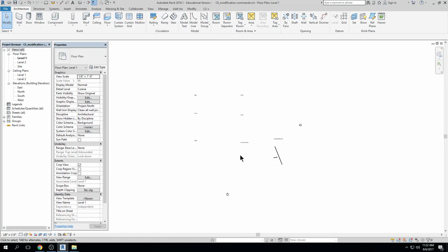So that's pretty nice. And that was obviously kind of the number one problem I had here, was my scale was off, okay? Now the second problem I have is that I know that I have information here, but the information is not showing, right? And this happens all the time. You have a lot of people working in the same file, and they are changing the visual styles of the file continually, right? So you need to know how to navigate that. Looking at this, I'm thinking, well, I know there was some information here, but I'm not seeing it. I'm seeing an elevation marker here and here, but I'm not seeing one up here or over here. So that leads me to my next assumption, which is my crop region is wonky and it's filtering things out that it shouldn't.